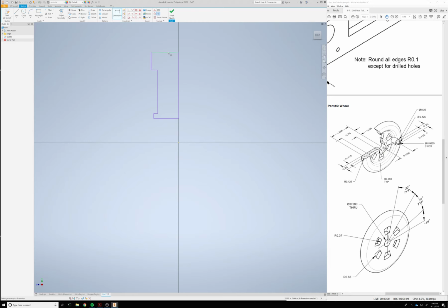Okay, so let's go ahead and add some dimensions. I'm going to put my overall dimension first. My radius is going to be 1. Okay, my inner hub, my inner diameter is going to be 0.28. So from here to here, 0.28 divided by 2, so 1/4. This guy up here, its thickness overall from front to back is 0.25. Okay, this thickness here from front to back is 0.125. And then the same thing in the middle right here is also going to be 0.25.